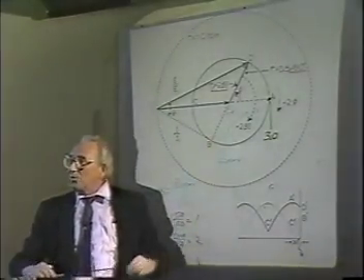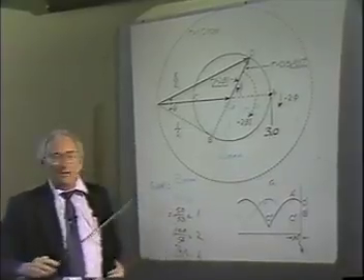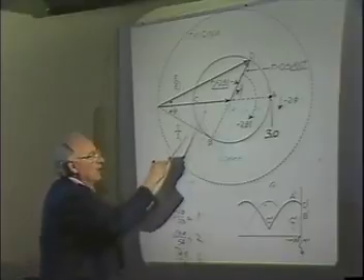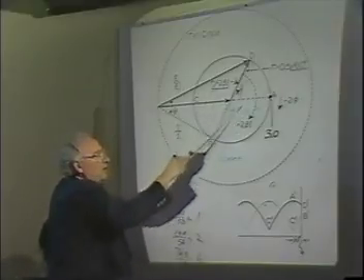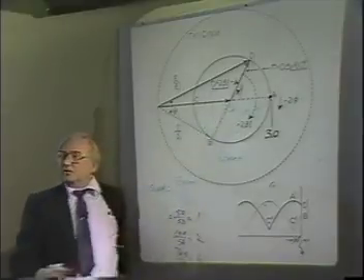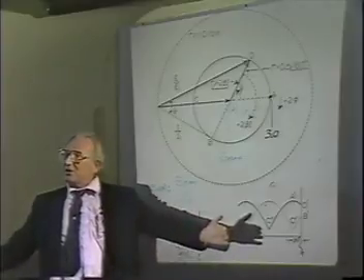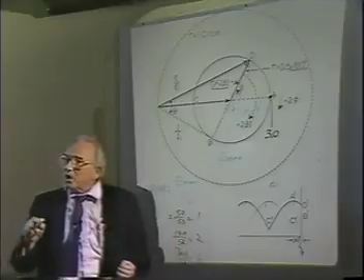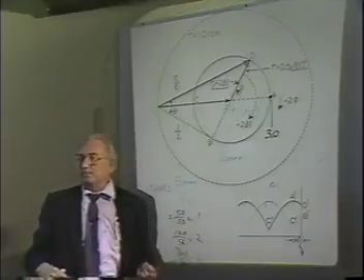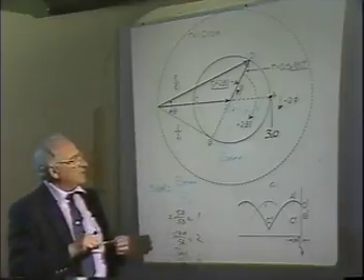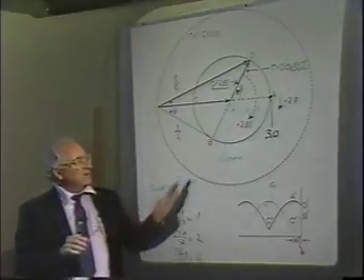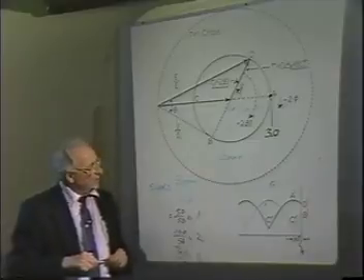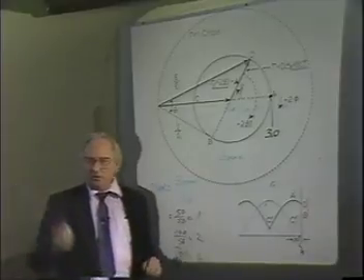So you see, this still holds with that return loss theory we looked at. If you go back on the line that has losses, you can see that the VSWR just keeps getting lower and lower and lower until it spirals into the center of the chart as a function of distance on a lossy line. That was the theory that I gave you in terms of actual problems of 3 dB, 3 dB, 6 dB. Okay, let's stop here just for a moment. I'll do some erasing here, and we'll do a little bit more looking into this and see some of the intricacies of this chart.